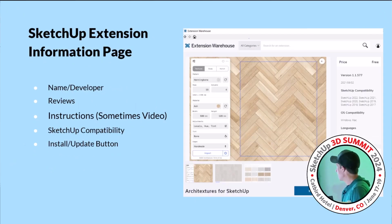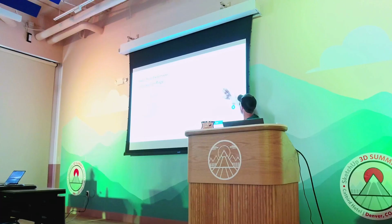When you go into the Extension Warehouse, every extension is going to have an information page that gives you information about the extension. So it's going to have the developer name, name of the extension, and some stuff over here about compatibility, which is kind of important, but not always important. Some extensions are not officially updated for the newest versions of SketchUp, but they work in the newest version. But it's usually worth checking. You're good to go if it says it has a SketchUp compatibility of 2024 and you're using 2024. If not, usually I recommend still trying to install it and then just uninstalling it if it doesn't work. But it is worth looking at.